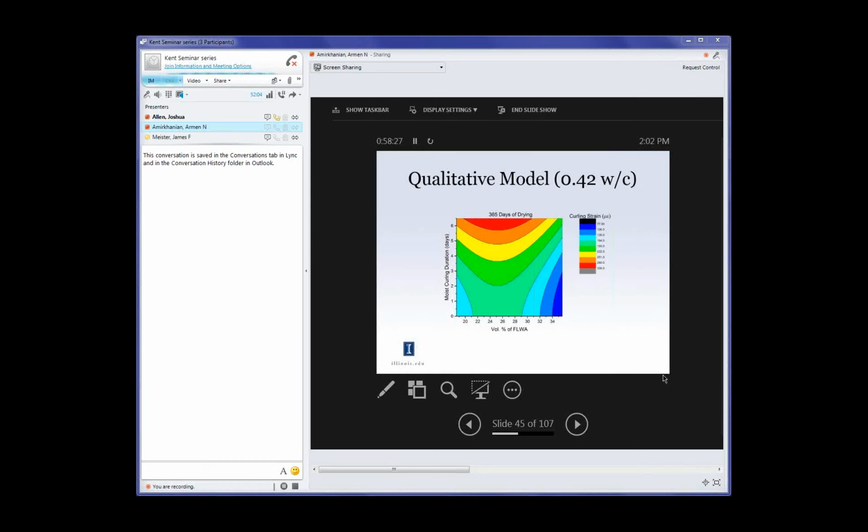Definitely. And we do have strength in the form of fracture properties like critical stress intensity factor and critical crack tip opening displacement, not compressive strength or flexural strength. But these parameters are much better at describing the true behavior of the material rather than, oh, this flex beam broke at this amount. We do have all that for each of these mixes. It's just not shown with this. But that could also push you to say, here I can get low strain, I can use less lightweight, which is cheaper because it's another aggregate source. But if this strength is half of this strength, well, okay. So yes, that would help guide you in another direction.